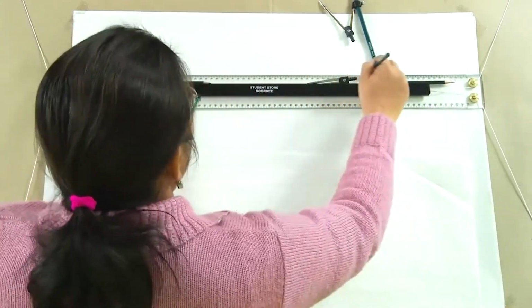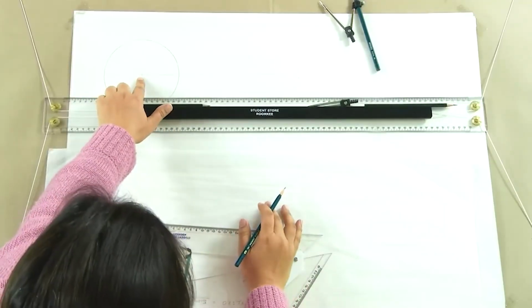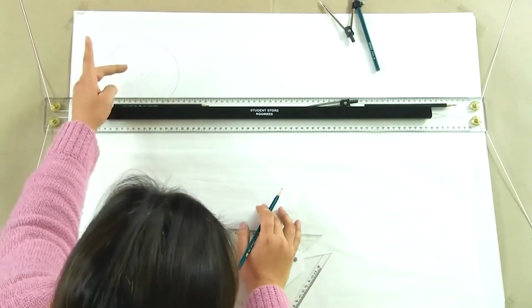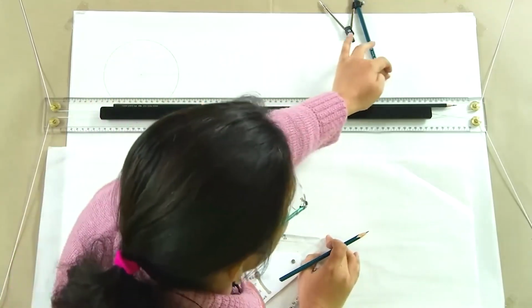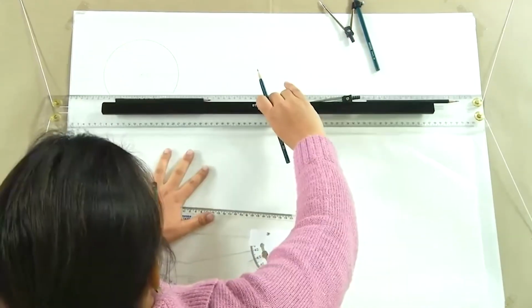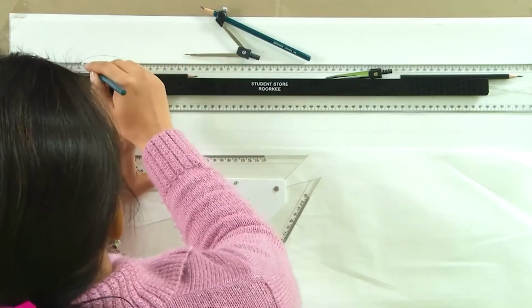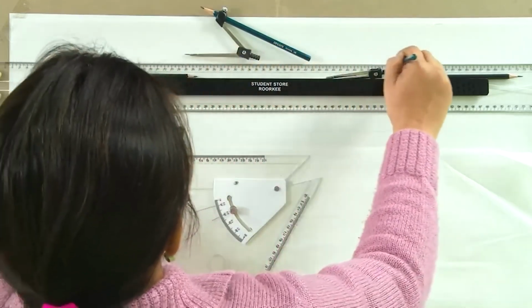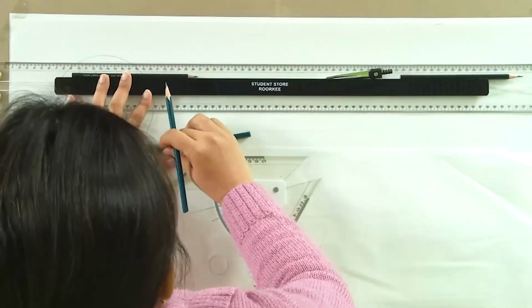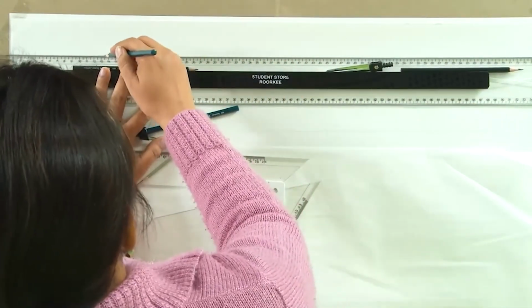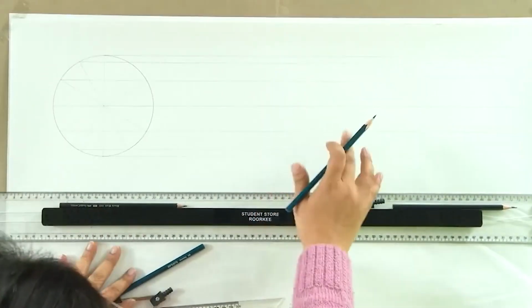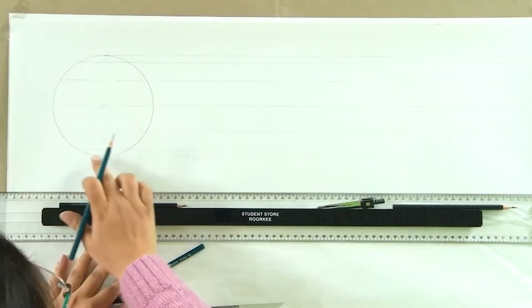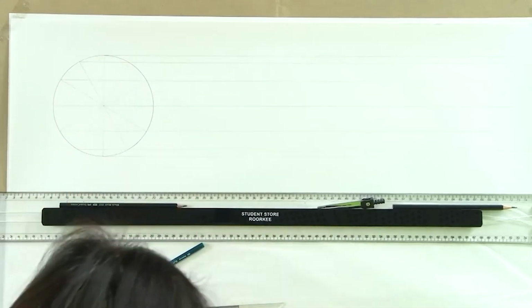This is the line which is passing through the center and also through 2 of the points. So, every time the circle rolls, the center of the circle actually remains on this line which is passing through the center. This is for cycloid. So, what we have done is we have drawn horizontal lines passing through all the points which were marked by these 12 divisions.